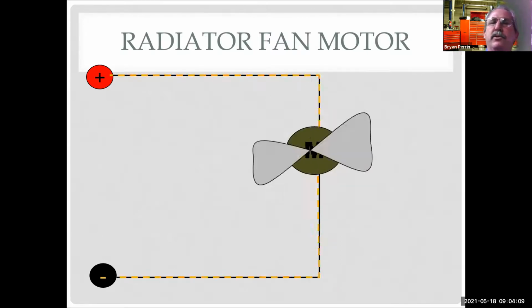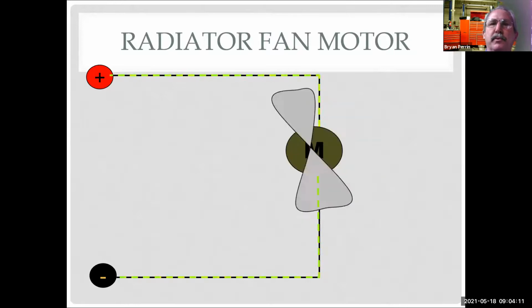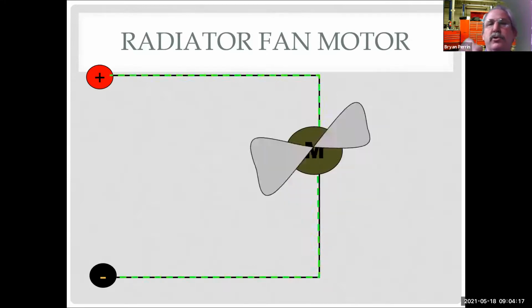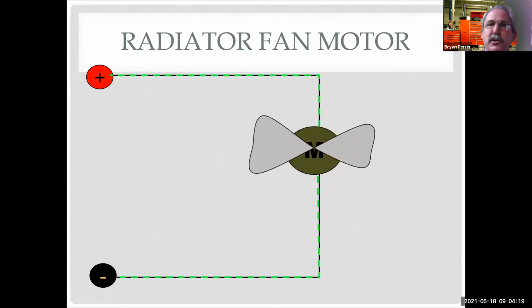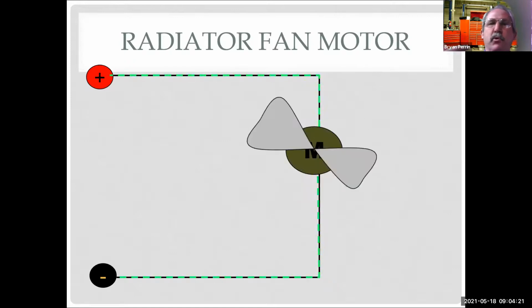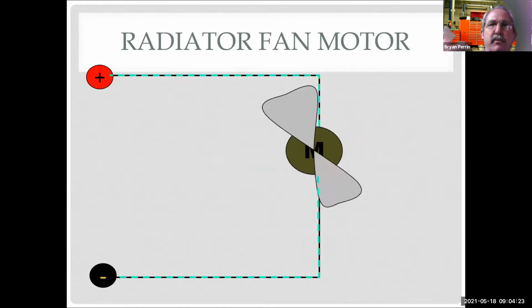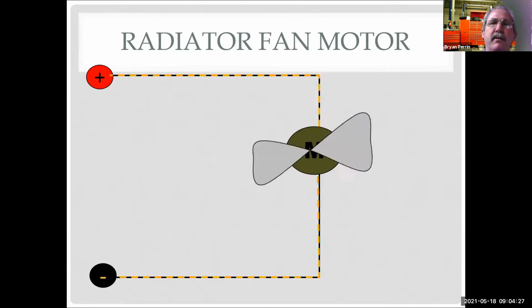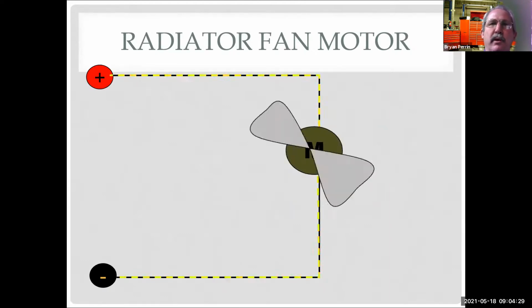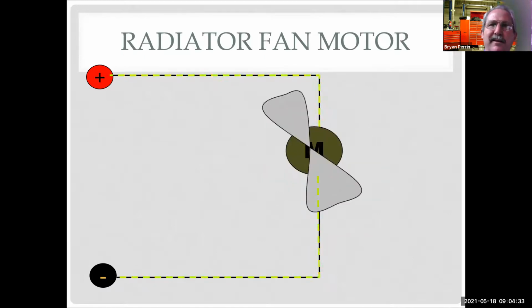Now we tend to duty cycle our fuel pumps because I want greater control of the fuel pressure. So in the old days, we just used to turn our pump on, let it run full speed, and we would just dump back the fuel we didn't need. So my pump's sitting there running at full speed all the time. Well, if I only need 25% of the fuel, why don't I only run my pump at 25% of the speed?